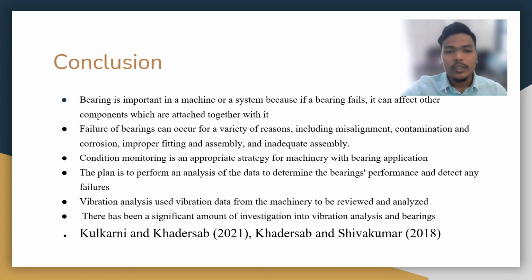Condition monitoring is an appropriate strategy for machinery with bearing application. The plan is to analyze the data to determine the bearing's performance and detect any failure. Vibration analysis is one of the condition monitoring techniques, other than lubricant analysis, infrared thermography, and acoustic emission. Vibration analysis uses vibration data from the machinery to be reviewed and analyzed.